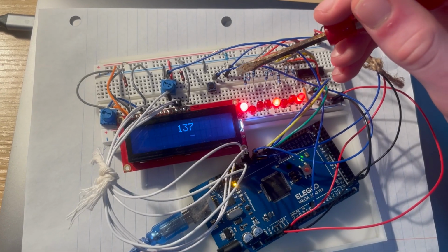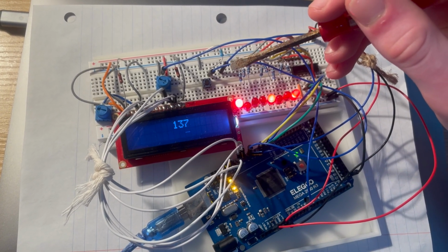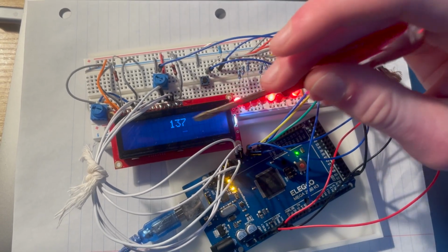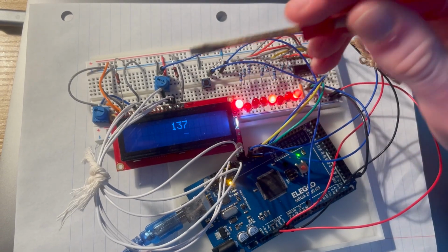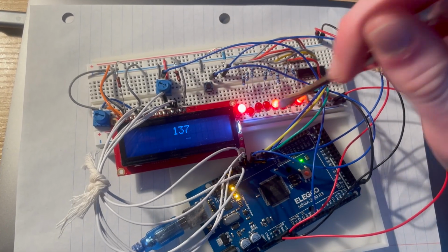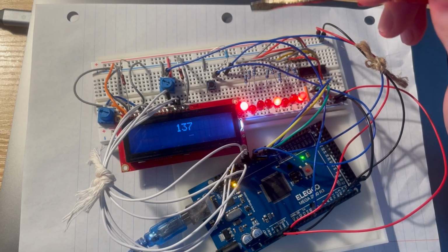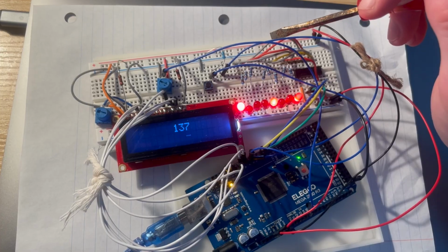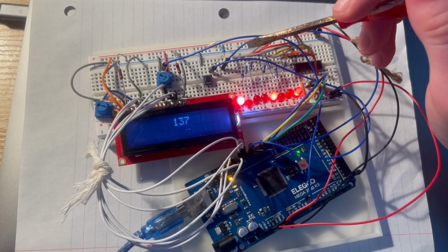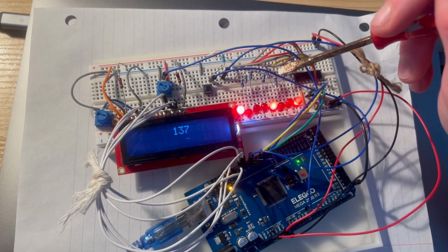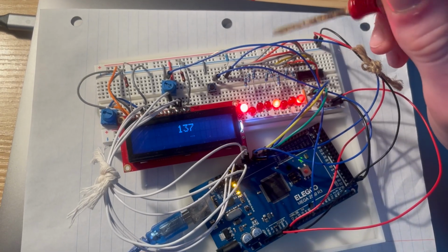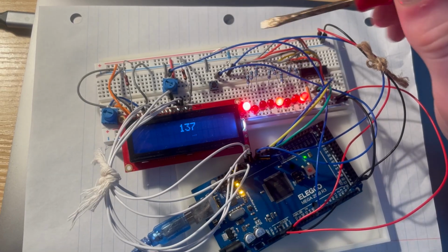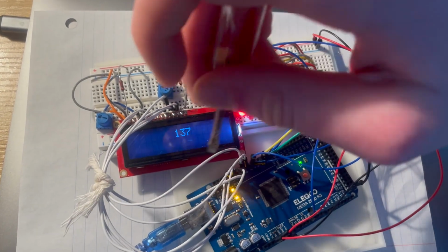Now, because there's only 8 bits of binary and thus it can't display a number bigger than 255, if you input a number bigger than 255 into the LCD, which you can, the array will be false, and it'll wrap around. This is actually a problem that happens in coding fairly often, that a number will wrap around its maximum value. So 256 will read 1, and 257 will read 2, etc. But to prevent that, I have a measure in place. It'll just say too big.